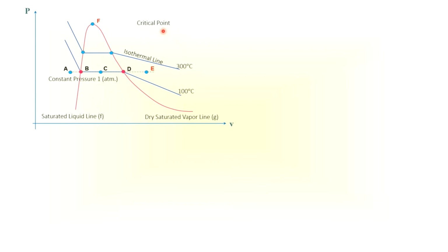The outer region at this part is called superheated. Around this part is called the compressed liquid. And here, remember, is wet. On this line is the saturated liquid or boiling, and on this line is the saturated vapor.